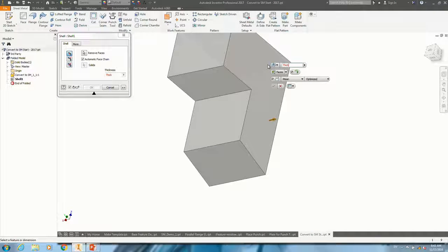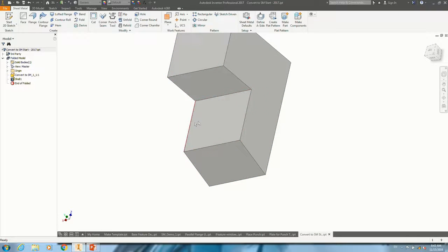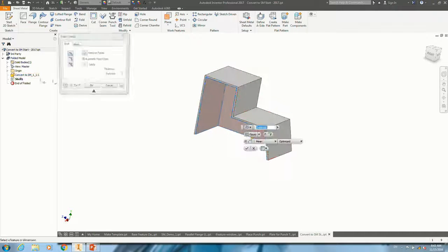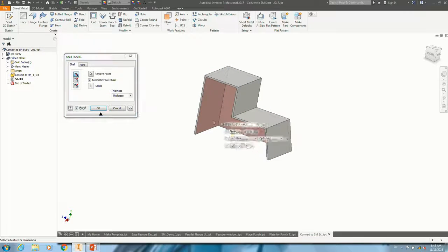Okay, so if you have defined the sheet metal rule or styles in the template, when you share the body, share the part, you can use the thickness from your defined rule as the distance. Yeah. Because this information is stored in the part, you can use the thickness directly as the distance.